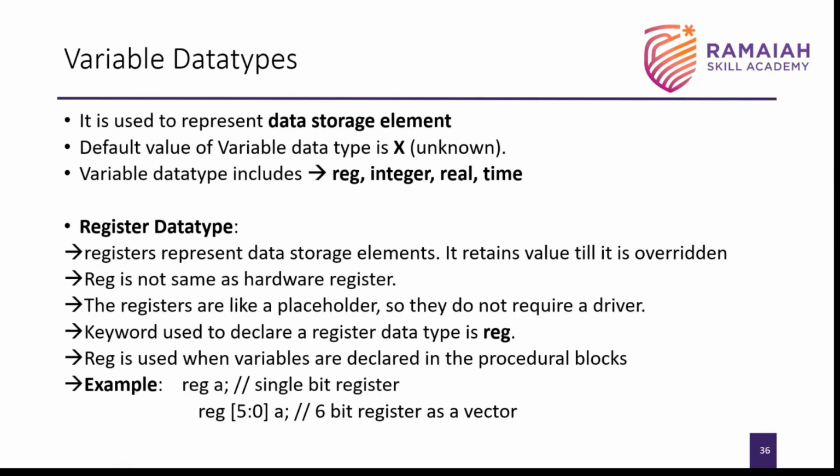And register data type is one of the variable data types, just used to store the values. And this can be changed throughout the simulation. Suppose you have here reg A is equal to 1. Then within the always block, I will change A is equal to 10. So it can keep changing. It may not be the same throughout the simulation. Okay, so registers are just used to store the elements. It can be overwritten throughout the simulation.